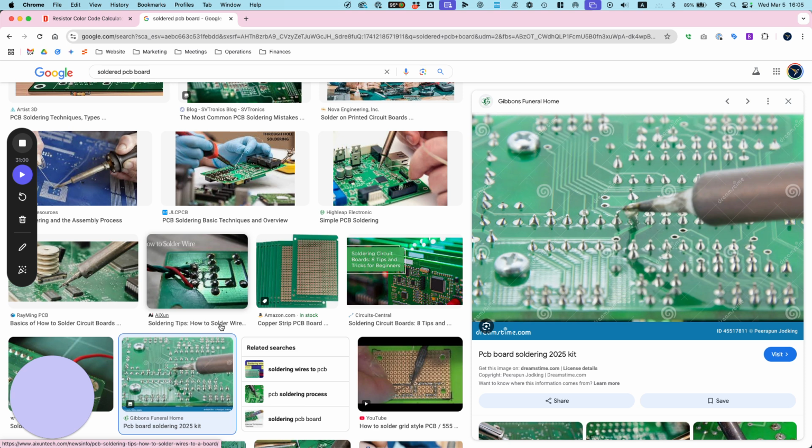Now if I go to the next one, 6E and 5A, they're not going to make a noise. So these also connect vertically. You see there's a break right here. It's physically a break. So this next one, 5F, G, H, I, J, those are connected to each other. These are connected, but they're not connected to each other. All right. Then we have a channel down here that runs horizontally.